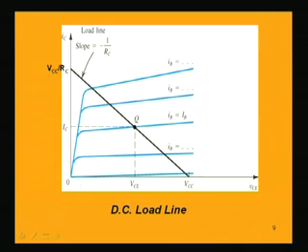So, we get a load line which is defined by these 2 extreme points, and this load line, if we draw on the characteristic curves, that is the output characteristic, the characteristic between the output voltage and output current, VCE and IC, then we know the intersecting point of the load line with the characteristic curves, where the characteristic is that one which is giving you the DC base current.